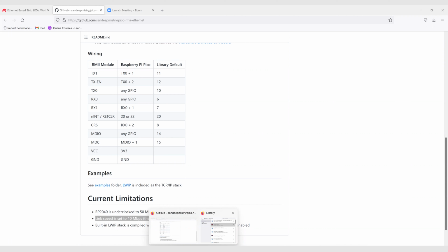that's the first thing you do with the PHY, is you configure it. So how he set it up to go in 10 megabit mode, that's in the code that interfaces to this MDIO. And we'll go over this a lot more next time. Now he originally planned to do MDIO with the PIO, but he didn't get to it. He just bit banged it.